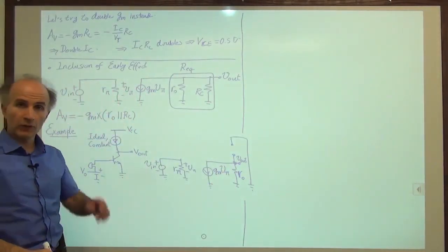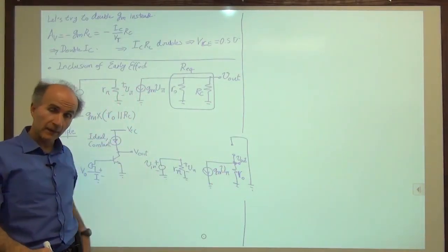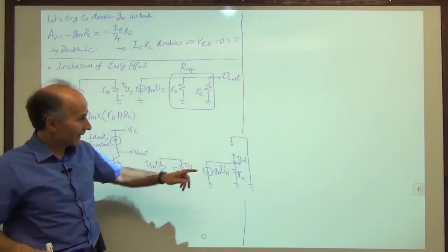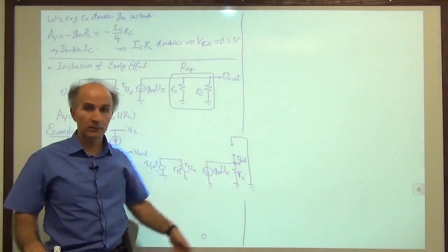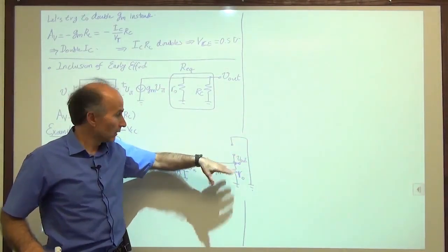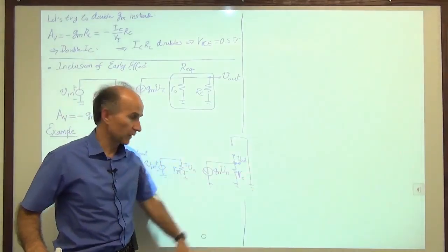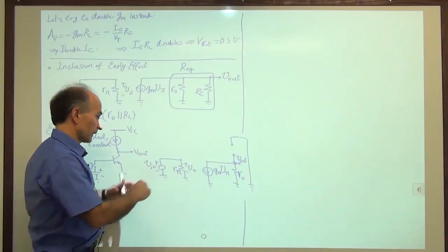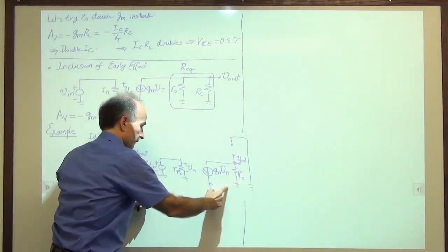So again, before writing equations, we just take a look and see what this tells us. Can we simplify it? What's the significance of this open circuit here? Nothing, it's gone. It doesn't do anything, it doesn't draw any current. So we can just forget about this piece of wire here. If you forget about that piece of wire, what we have is just this nice little circuit.